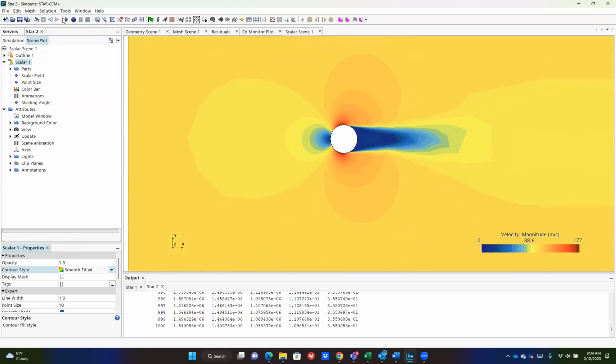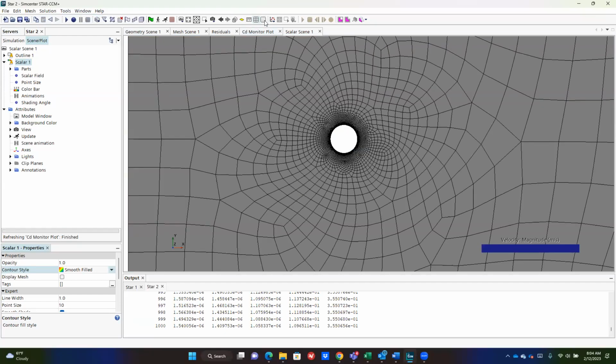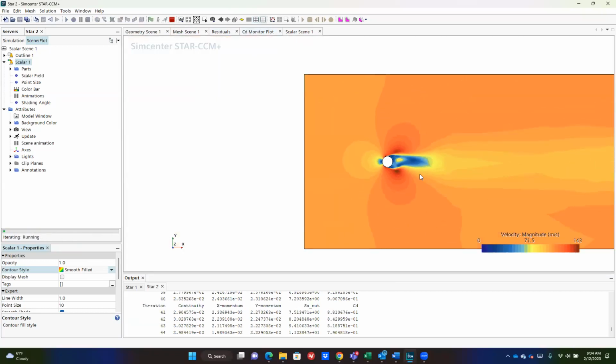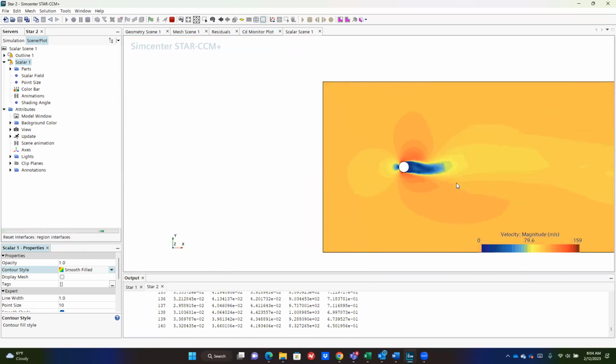So I'm going to clear the solution and just show you this. So when you're done with your solution, you get a solution, clear. Now you start from square one. I'm going to rerun it and show you. You could see how the model is evolving. You can see some of the unsteady characteristics in the solution. Recall we used a steady model, which is very invalid for an unsteady flow. And you could see it converging.